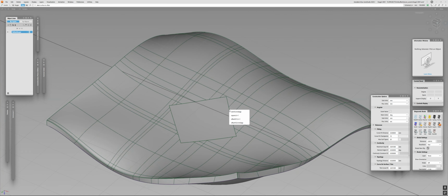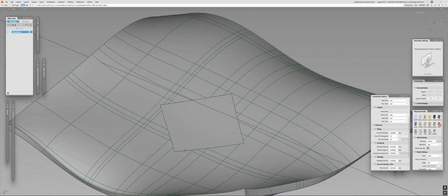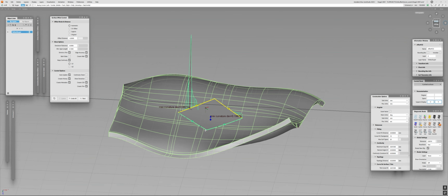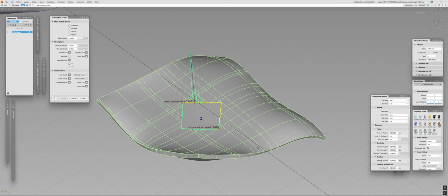So we have our deviation. Actually, no, it actually helped us. Yeah, no, it actually helped us. Not necessarily very much, but at least we removed the positional issue. So well, that's it. And once again, that's because it takes these edges and uses the same edge accuracy as for this surface, and basically it's pretty tight. So don't forget about this tool. This option can be helpful sometimes, especially when your surfaces are trimmed.